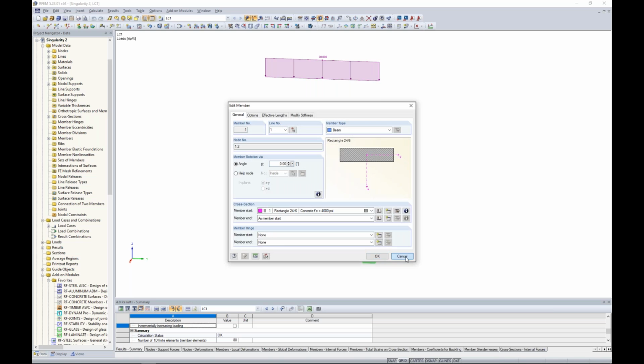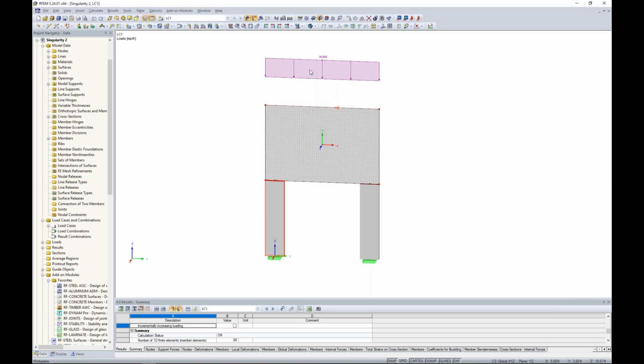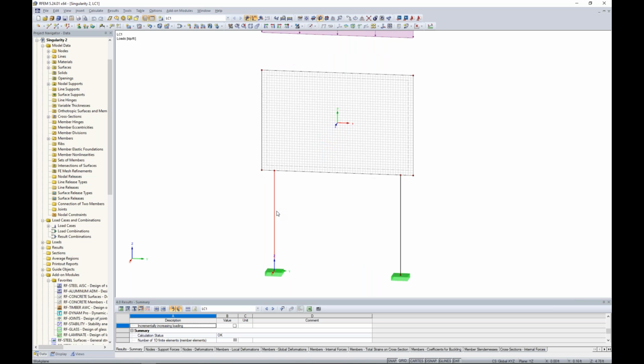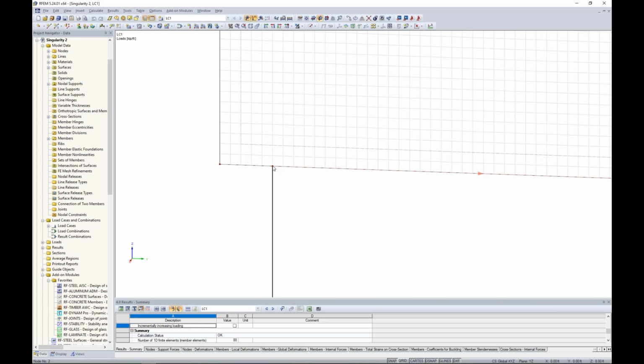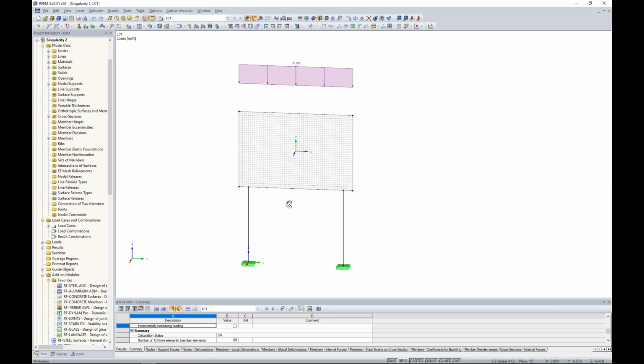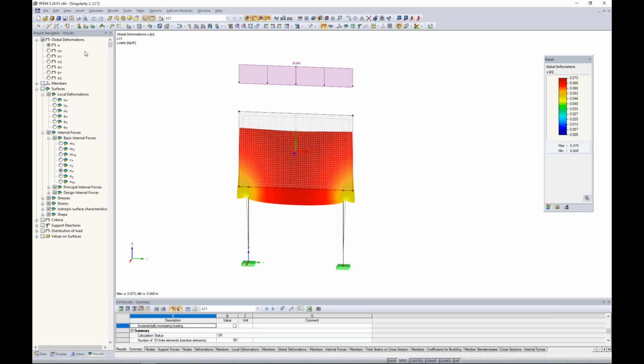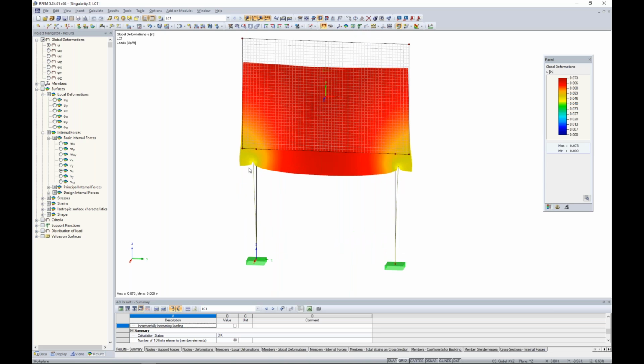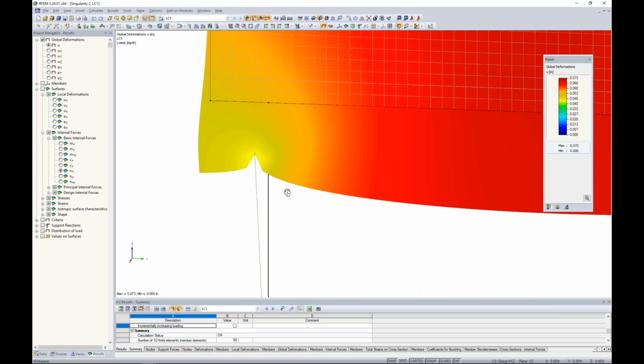Now these columns are quite compact, we'll say in one direction, 2 feet by 6 inches. But regardless of the dimensions of this column, when we turn this to wireframe view, we'll still see that these members are represented by these single line elements framing into this one tiny FE mesh point here. So when we take a look at the results from this first load type, and we're currently viewing the deformations, we zoom in here to look at our deformations.